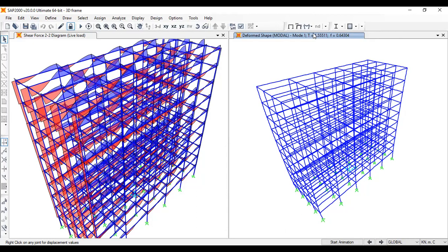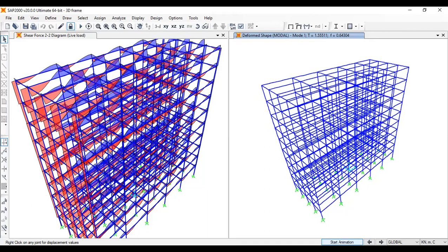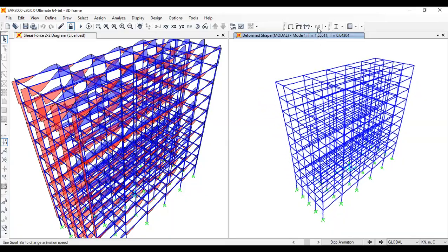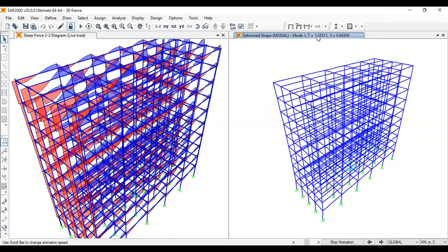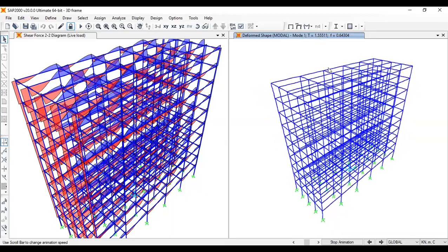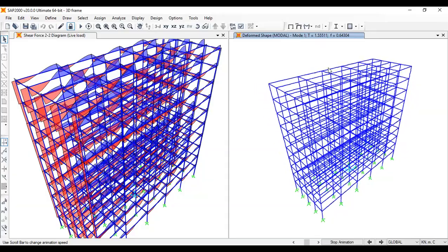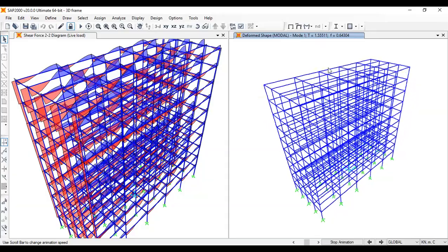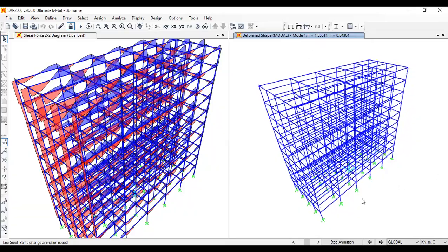That's not good. What that fundamentally means is your structure is going to be oscillating for a larger time, right? So T is 1.5, it's not that much. You need to reduce T to around 0.1 into the number of stories, that means 1 second. Okay, so you have to know these things. It's 0.1 second per floor.